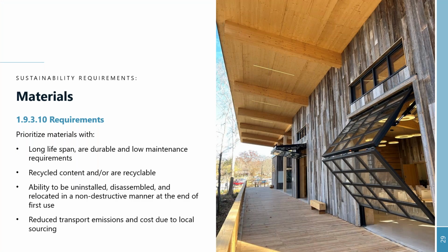All right, I'm going to shift now to materials. I think this was the other big section where changes have been incorporated or requirements have actually been bolstered within the P100. There's always been a focus on prioritizing material selection, looking at the durability, the life of the material, and the low maintenance aspects, but also recycled content, and or if the material is recyclable, so it can continue to serve a purpose in the future. More now is this ability to disassemble, uninstall it, and reuse it in its state in another application, and also local sourcing to reduce the transportation emissions associated with the materials.